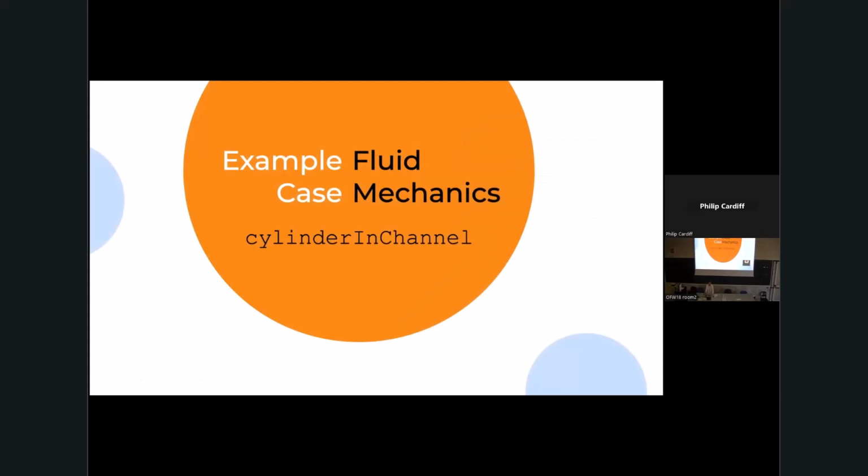Okay, I'll keep this part brief. You're not going to use solids4foam for doing a fluid analysis by default, but since we have to do FSI, you can actually do a pure fluid analysis in solids4foam as well if you wanted. So why would you do this? Well, if I port a new fluid solver, I might want to benchmark it and check it gives the same answer. There's only one tutorial called cylinder and channel.